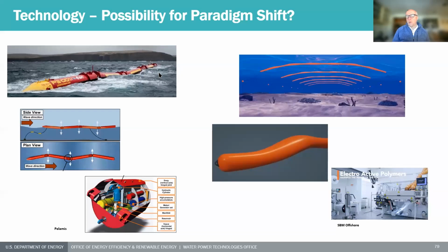I think oscillating water columns are a very good example. It's a very obvious solution when you see it, but it's non-intuitive. It does very many things. It's an internal gearbox: a large body of mass that's moving slowly is converted to the same volume, but a very fast flow in a narrow duct.